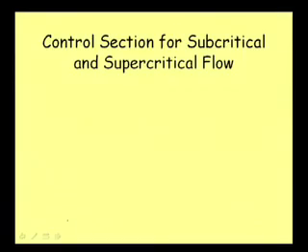In the last class we did discuss the control section, and then we were talking about how a supercritical flow gets affected only by the disturbance that we create at the upstream of that, and subcritical flow gets affected by the disturbance created at downstream of that flow section. So, let us go to some more detail of that particular issue.